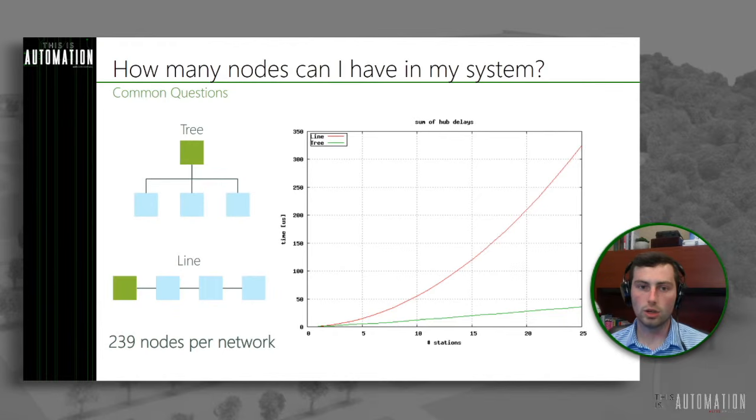All right, so we talked about topology not too long ago, and we looked specifically at a tree or a line topology. A lot of Powerlink devices have these integrated hubs or integrated switches so that you can daisy chain from node to node, which is great. It makes cabling super simple, but there are impacts to your timing. Again, timing is kind of the important thing here, depending on which system you're looking at.